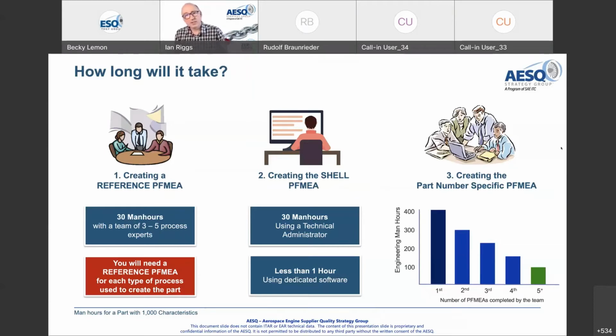And what we've seen, and the examples of the suppliers who presented at the supply forums have shown, is you can actually make a step change, not an incremental change, a step change in quality performance as a result of using FMEA, changing your process to take account of that, introducing mistake proofing or statistical process control on those things that are marginal capability, and maybe having more leeway in how you control things where the capability of the process is much better.